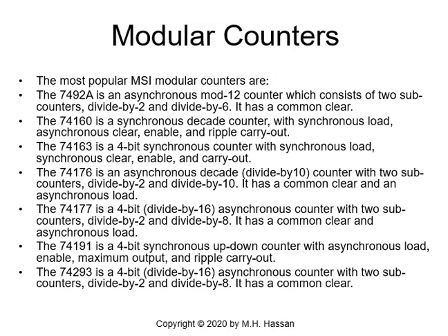As you see, many integrated circuits have asynchronous load, not synchronous load, because the design is quite simple. The 74163 has a synchronous load and synchronous clear, enable, and carryout. So there are a variety of counters available for use if you need them.